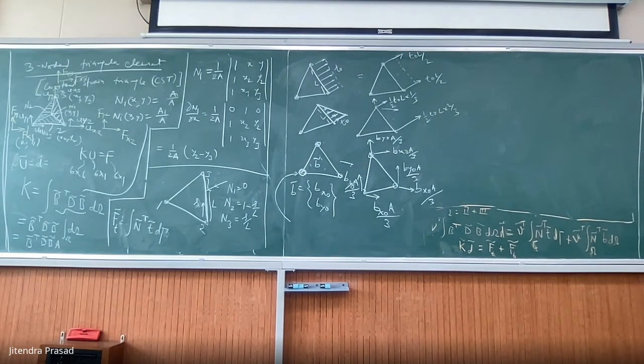Yeah. So this is the insight. Don't be lost in equations, right? This is the physical meaning of that. Finally, we are working with what? Only 3 things. The stiffness matrix, which is like a spring, as you understand. Then displacement, it can be fixed, or you have to find out how much it is. And third is the force. There's no other things coming here.